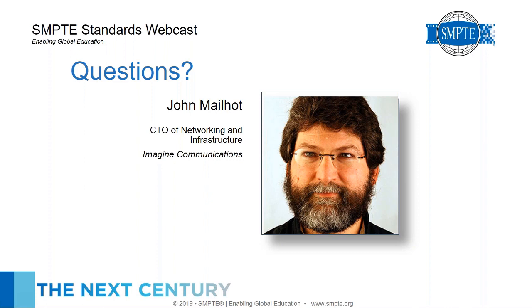Sure. I know too much about IS-08. So IS-08 relates to audio channel mapping. IS-05 that we just talked about lets you tell a receiver to take a certain audio stream. But typically these audio streams have multiple channels of audio inside them. And so IS-08 is an API that in a standardized way lets a controller manipulate the mapping between those channels that come out of the audio receiver and whatever internally is consuming it.